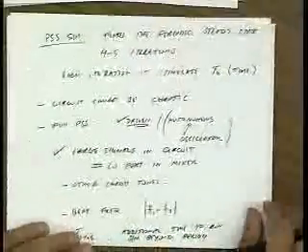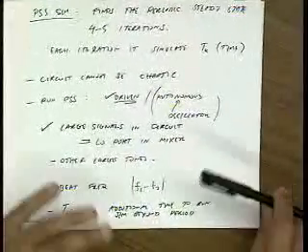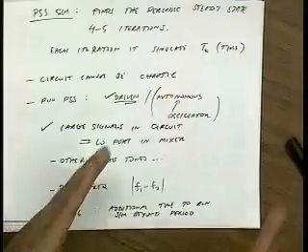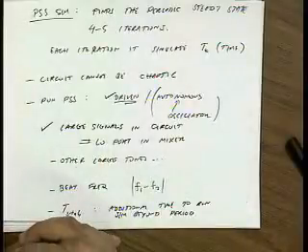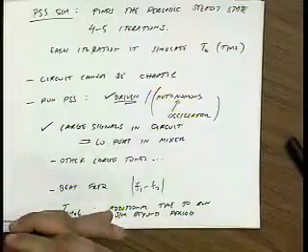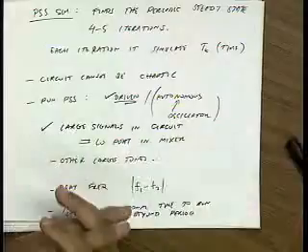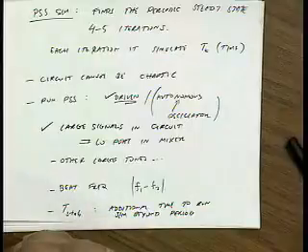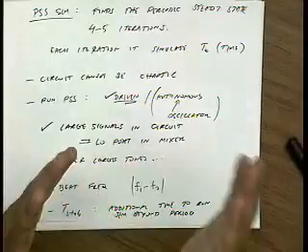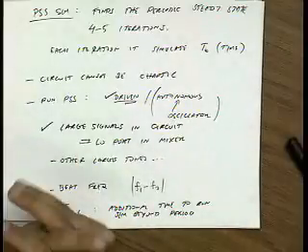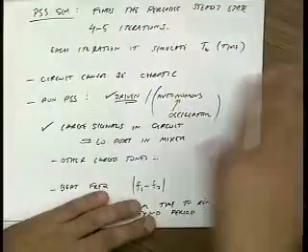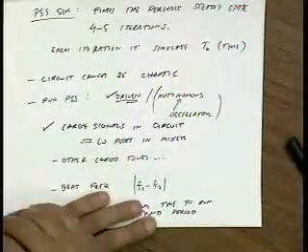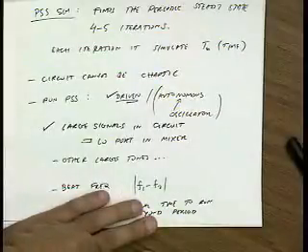Okay. So any questions up to here on what periodic steady state analysis is? So let me just repeat. We haven't said anything about mixers. All we've said is periodic steady state analysis tries to find the steady state periodic solution. Okay? And if you think about normal SPICE, there's no way to do that unless you simulate it for a long time. Now some circuits get to periodic steady state very quickly, okay? Because, for instance, let's say I have just R's and C's in my circuit, critically damped. Few cycles, boom, the transients died off, right? Let's say I have lots of poles in the left half plane, and they all have very short decay times, so they all decay away, and I get to periodic steady state. Other circuits, though, let's say high Q circuits, take a long time to reach periodic steady state.